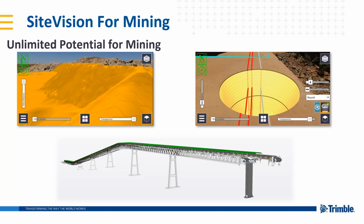The survey team also are able to take ownership of utility locating. This is an actual screenshot from site again of the utilities running underneath that footpath. We've got some power cables on the left and communication cables on the right in gray. Other items that they're looking at doing is the positioning of plant. IFC models are very common in that sort of area and work nicely in SiteVision. So the positioning of plant, also exploring whether you can fit plant in certain areas.